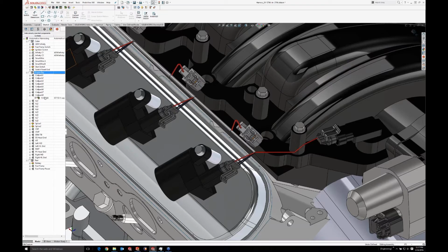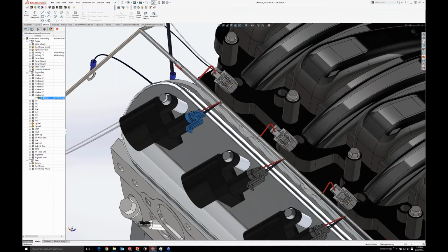Contained within the electrical component is a link to a 3D part file. So you can see that it looks like the SOLIDWORKS assembly icon. If I had placed all these one at a time into my project, I can just right click and insert. But if these were already placed, a lot of my customers have already started doing some electrical routing, or they've started having some of their connectors in their drawings just so people can see where the connectors attach. All I would have to do is a right-click associate. So here this is already associated, so I can disassociate it. But if this was not associated, you would say associate, click that, hit the green check.